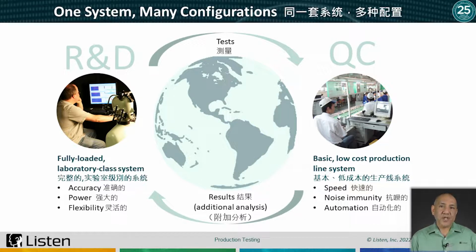Maybe you want to perform directivity tests, for example, polar plotting on-axis and off-axis response using automated turntable control or a multi-channel horizontal and vertical microphone array. In short, you have ultimate flexibility for all kinds of parameters, even the unknown. These are all important tests in R&D, but impractical on a high-volume production line.